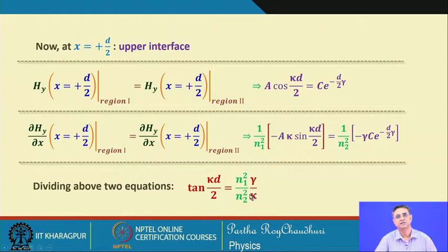Similarly, this is the x component of the propagation constant for the core, which is associated with the refractive index of this. So, in this form it appears in the eigenvalue equation for B equal to 0, that is for the symmetric modes, cosine function modes.